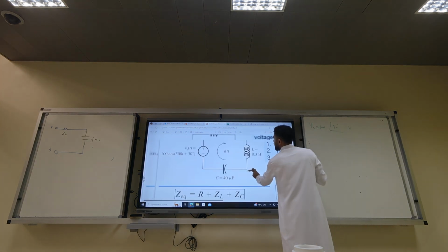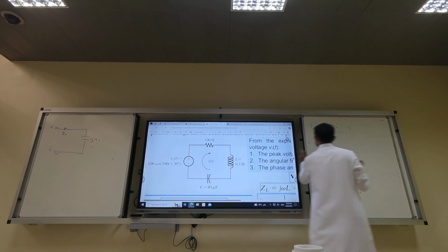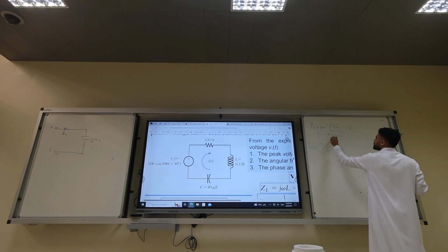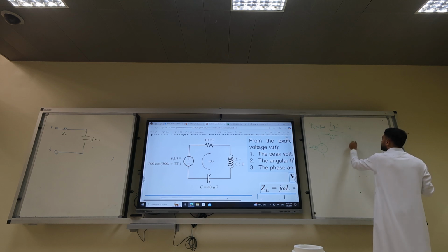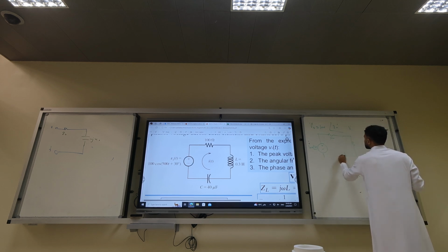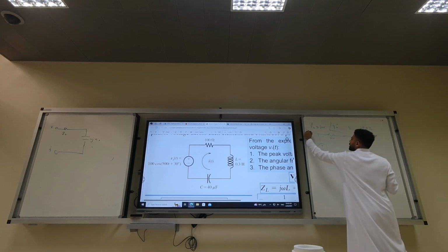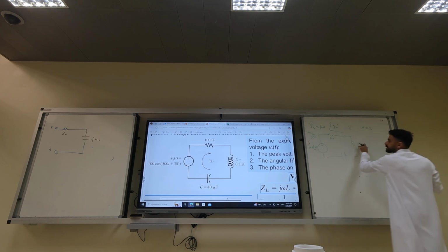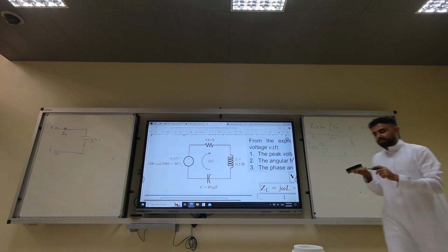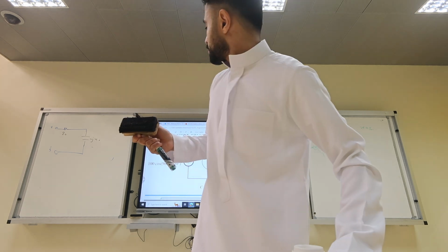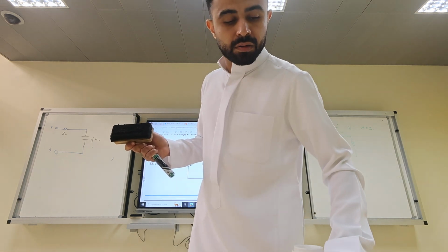Now we are professionals, right? What did we say the first step? Convert. So you can say this is 100 angle 30, and then we have a resistor. We keep it, right? Yes. Please, how about the inductor? What is omega? 500. Always write omega here, okay? Because you needed to calculate 0.3 times 500. 150. I want to verify. Yes.